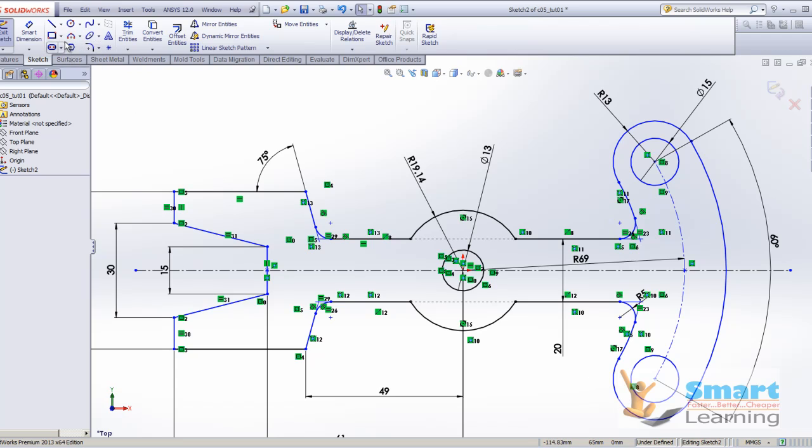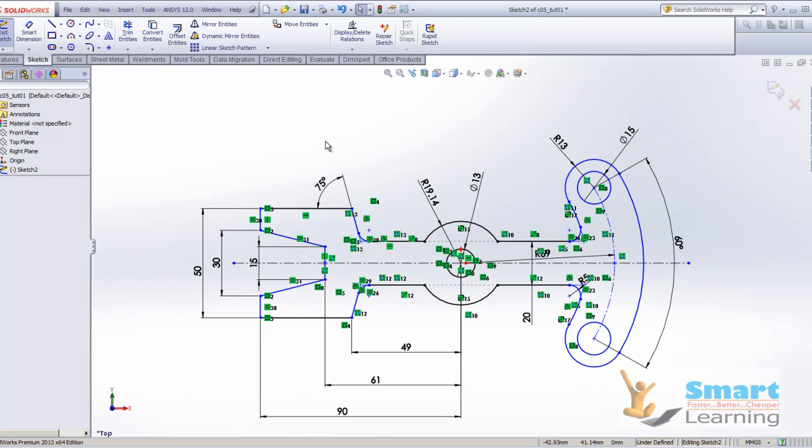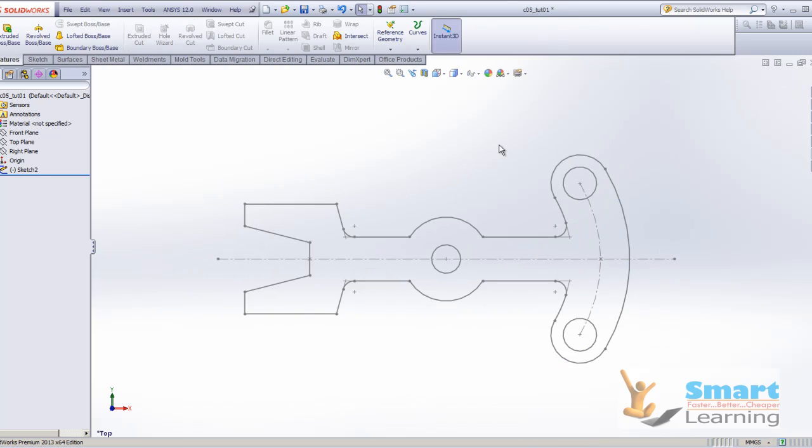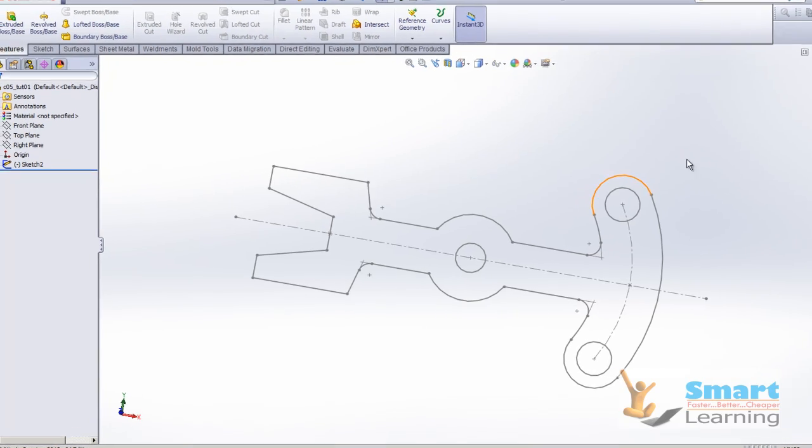So this is very simple. You need to go to this particular center point arc slot, and then you can position with respect to this center, because from this center only this is created. And after that again you trim the required portion and update this sketch. So once you get this, you can apply your extrusion. Whatever the extrusion our target is, how to create that, I will show you.